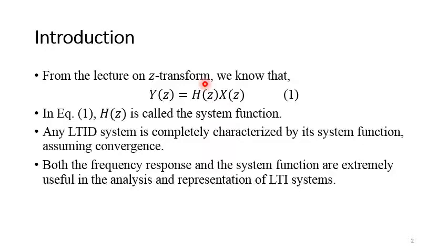So just like in time domain, we say an LTI system is completely described by the impulse response. What do you mean by characterization? That means we can tell about the character of the system. Character means whether the system is stable, unstable, causal, non-causal, with memory, without memory, and so on. All these characteristics can be extracted from the impulse response of the system.